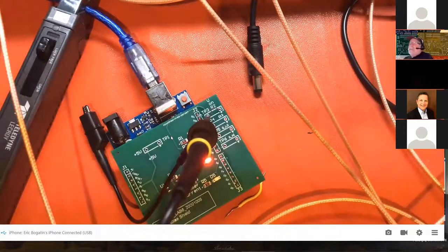And when you look in the time domain, if you have a synchronous signal, as we used here, you can look at what the currents flowing are and the near field emissions from those currents, associated with that synchronous signal or other signals that are synchronous. Oftentimes, if it's repetitive, that's where you can use averaging. And that 12-bit resolution means that you can pull your signals out of the noise much more easily than if you had 8-bit resolution. You can zoom in on those features. And looking in the frequency domain means you have a little bit better dynamic range because the digitizing noise floor is going to be dramatically reduced with 12-bit.